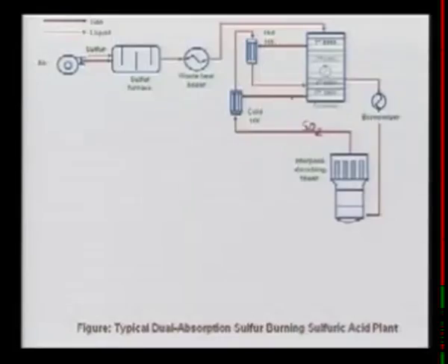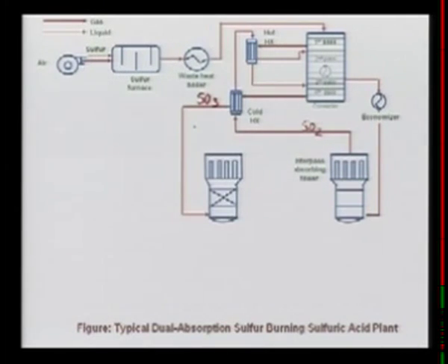So, here what you do is you bring it down, and you make it cold. This was the heating part, this was the converting part, and again cooling of the gases, because now we want to take this one. So, again what I am getting here is the SO3. This SO2 which had become an excess, I converted it back to SO3. What it needed was to heat it up, then convert it, then cool it, because only the cool gases can go to my absorbing tower, and bring it to the next absorbing tower.